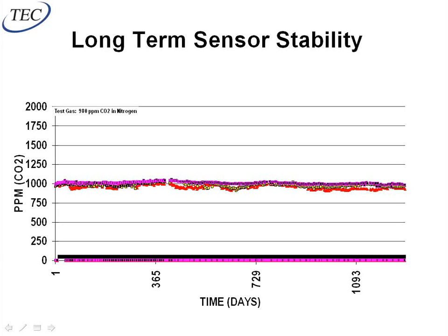However, if I've opened up that damper as far as I can and my CO2 level has not come down, then that box can report back to the air handler that it needs more fresh air, and that damper on the air handler will start modulating open. So basically, each VAV box gets controlled to its own CO2 sensor to modulate between its minimum and maximum CFM set points. And the main air handler itself is only looking at the worst out of all those boxes. So if I got 25 VAV boxes on one air handler, I look at all 25 of those with the DDC system, figure out who's the worst, and I control my outside air damper to him.